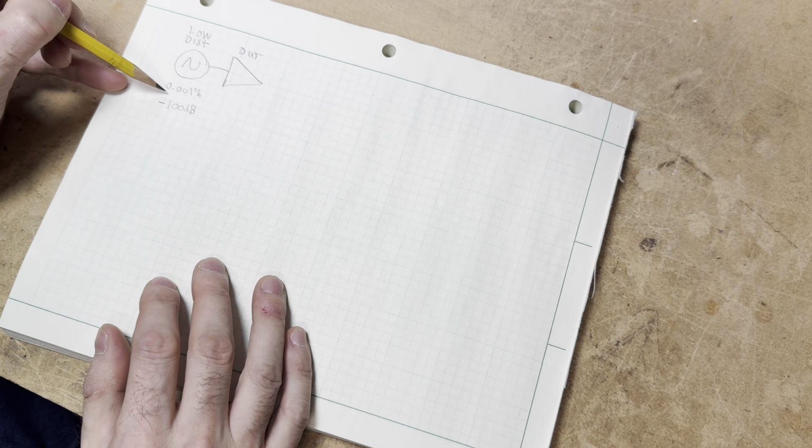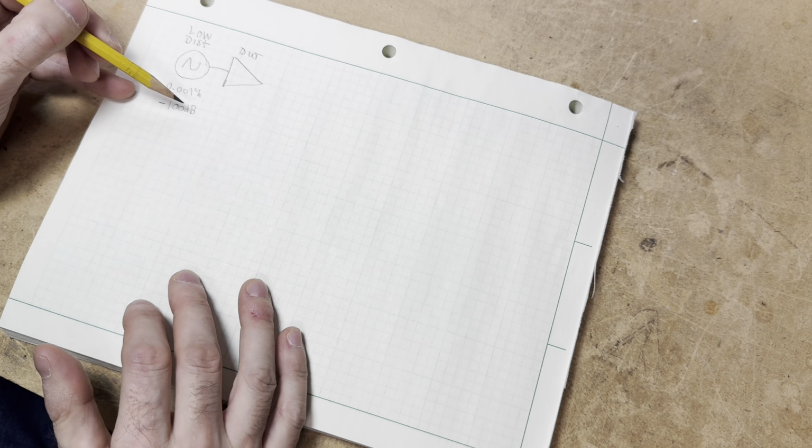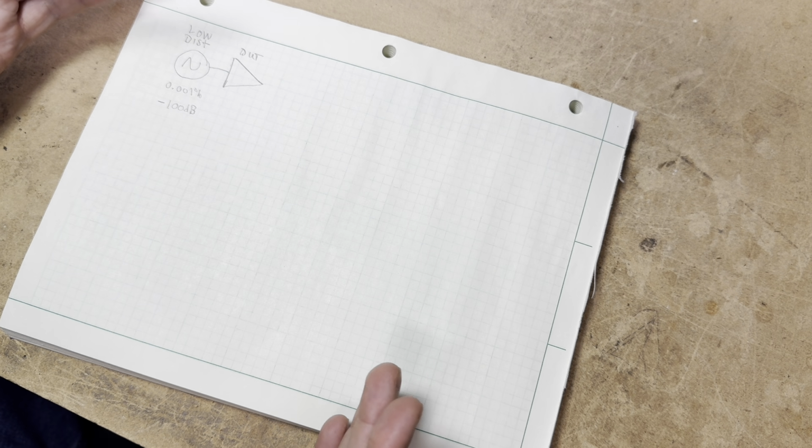You could probably get away with making a measurement with a source of, say, maybe only minus 80 dB or 0.01% distortion, because you're still well below the floor and your device is going to contribute that much more to the distortion. So you're not going to really need that extra room to the floor.